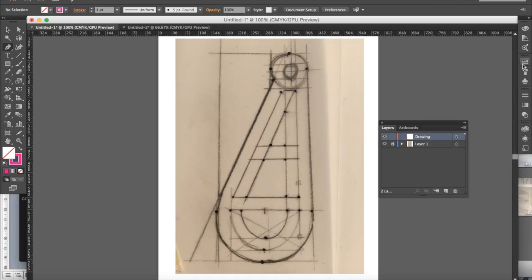So for example, here on the toolbar on the right hand side there's colour swatches. These two blocks at the top here, one is for the fill and one is for the line stroke. So we want a line stroke that is a different colour, so in this case I'm picking pink, and please make sure there is no fill.